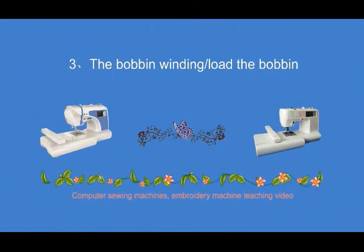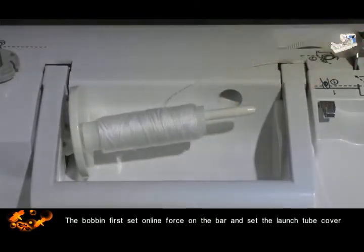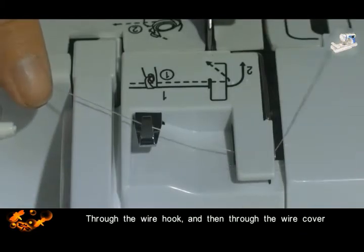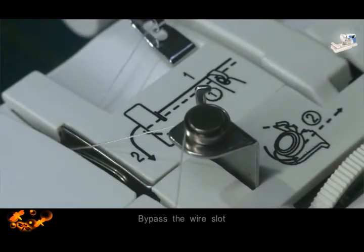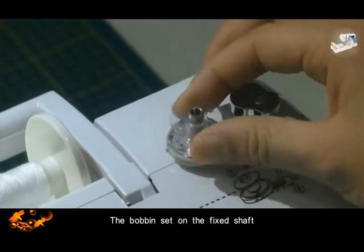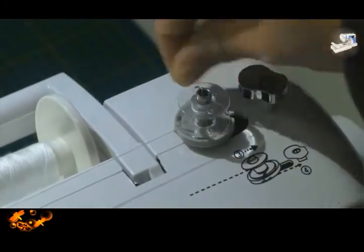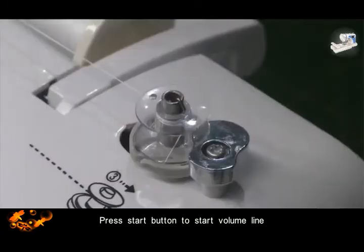3. The bobbin winding/load the bobbin. The thread first set on the thread rod and set the thread cylinder cover. Pass the thread along the path on the icon, through the wire hook, and then through the wire cover. Bypass the wire slot. The bobbin is set on the fixed shaft. Wind the thread around in circles on the bobbin. Push the bobbin to the right. Press the start button to start winding.